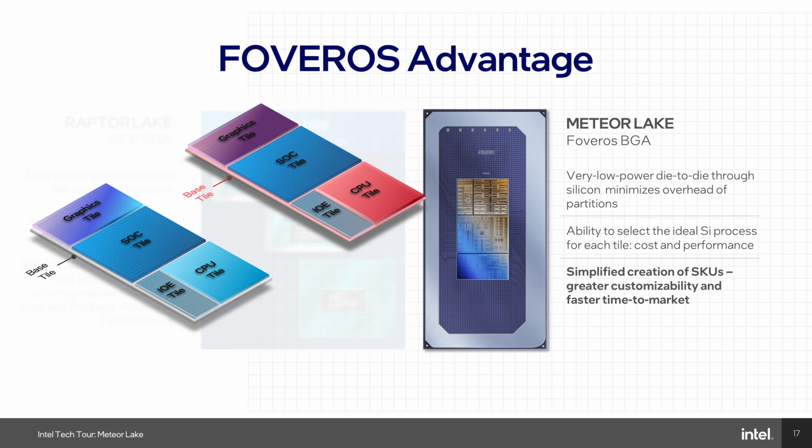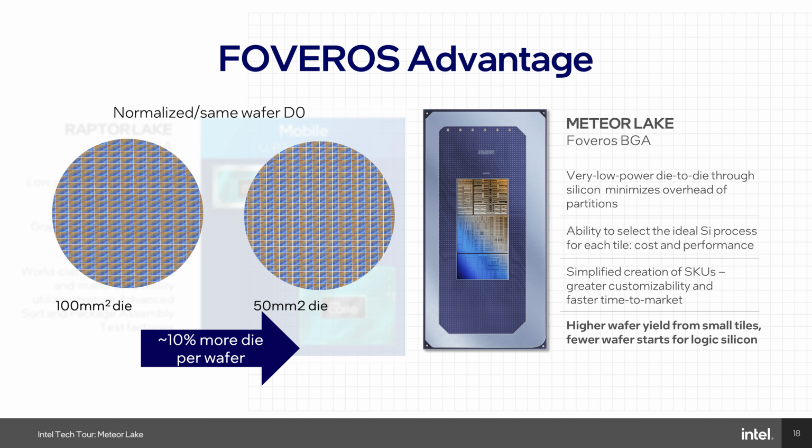So this is another good reason to do disaggregation. One of the aspects of disaggregating is that you control the die size, okay? You don't have a huge part. Die size, when it's big, usually reflects to lower yield. So smaller dies have a better yield, and especially when you go to the leading node, you care about yield. So this is another reason why disaggregated is important.